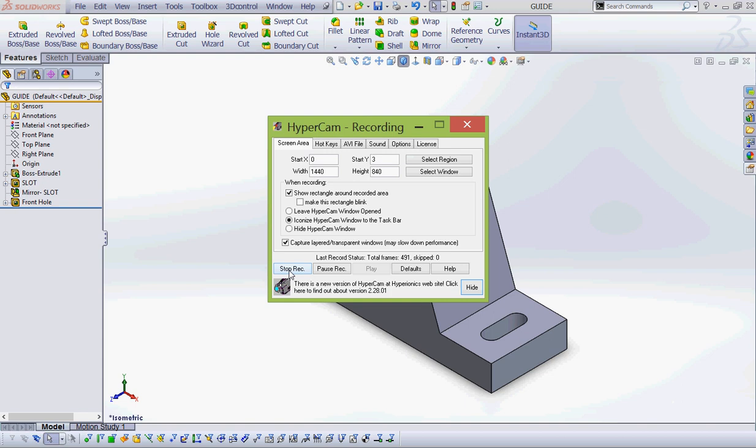So I just hold down my control key, I select the center point, I select the origin, and then I can say vertical. If I hold the control key and make my two selections, then it'll automatically know that I'm adding a relationship. Otherwise, I have to go up to the ribbon and select add relation, and sometimes I find it faster to hold down the control key, just say what I want it to be. Then as soon as I add that relationship, it says fully defined.